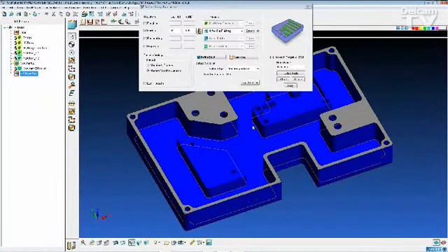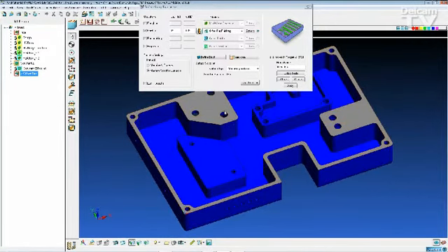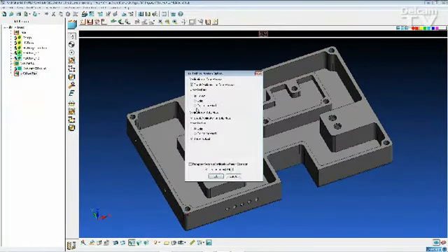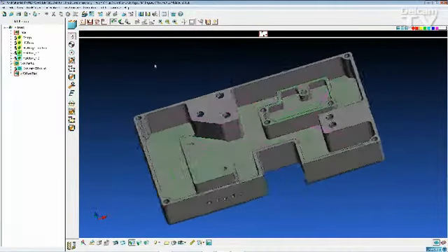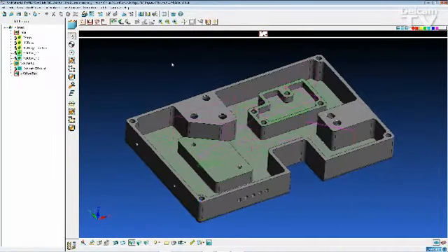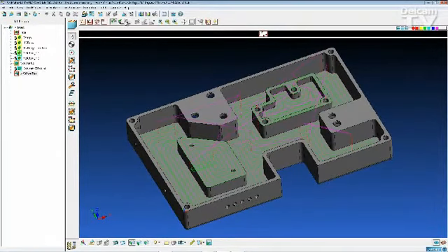We also have some horizontal machining strategies, such as offset and flat finishing. So here we're going to do offset flat, which finds all the flats except for the top surface that we've avoided. And we could also change this strategy.